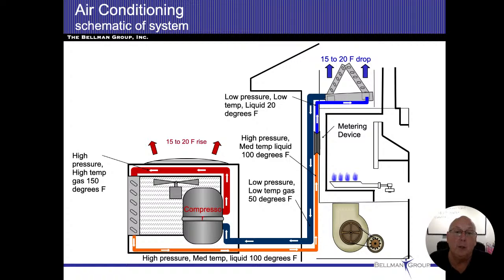If you look at this kind of carefully, you'll see that that compressor, and I'm not talking about the fans that go ahead and blow the air over the coils, the compressor is really the only moving part of the air conditioner. So as I'm adding pressure into the system, I'm also releasing pressure at that metering device. And those things are supposed to be in tune perfectly.